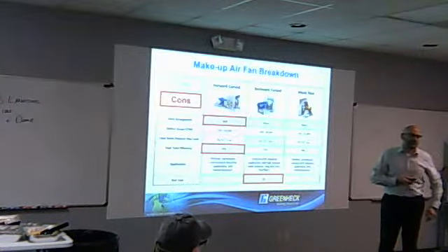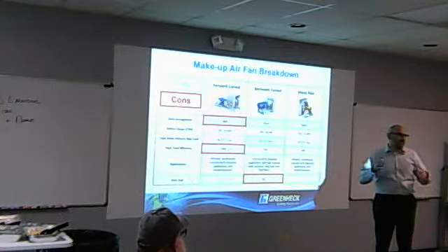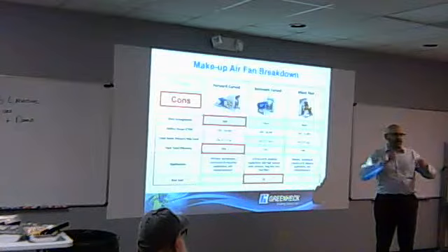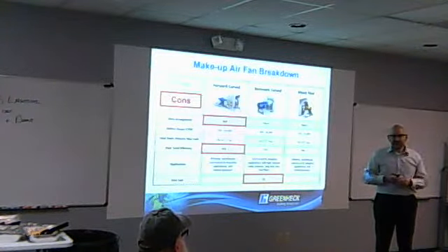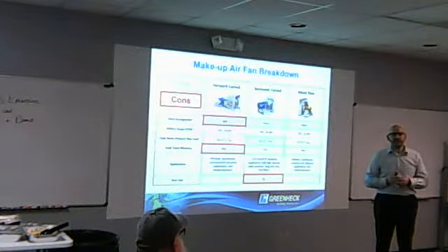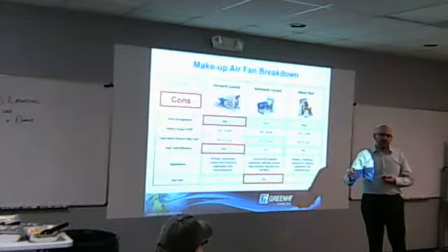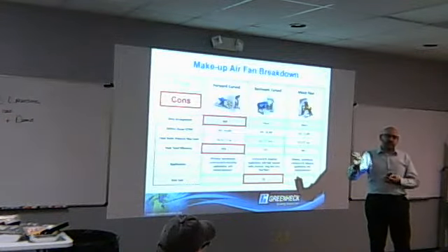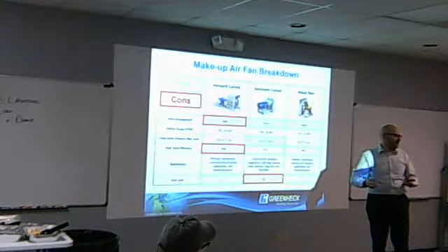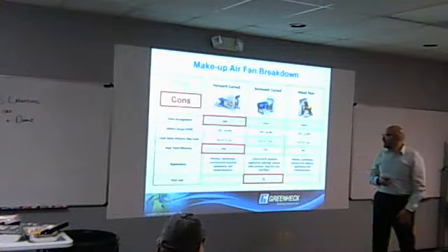10, 15, 20 years. There are certain ASHRAE charts that publish expected lifespan of equipment, and I think they list rooftop units at 10, 12, 15 years, maybe 20. We keep that mindset and try to get the most efficient. Now, sometimes in our software you'll get 7 or 8 selections and you might get 10 or 20% more efficient, but it's 3 times the cost, which is probably not going to fly. So we moderate that and keep track of it.